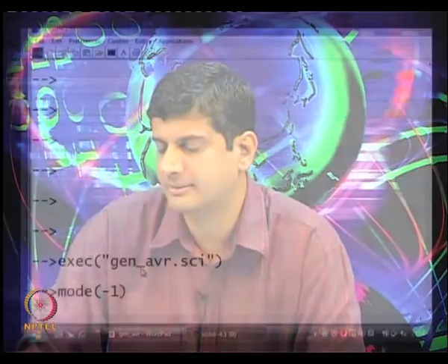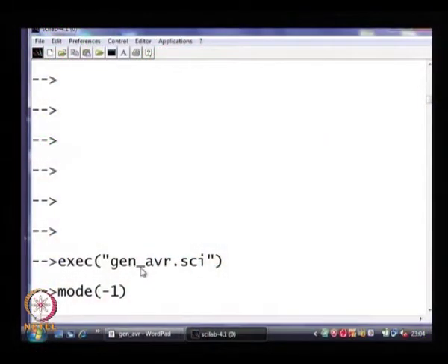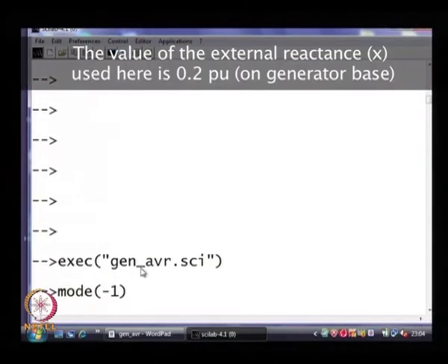Okay. And after 15 seconds, of course, the step in real power will be given at 5 seconds. After 15 seconds, we will give a step change in the reference value of the AVR. Okay. So, that is what we will simulate and close this lecture thereafter. Okay. So, if I simulate this, I am simulating for 25 seconds with Euler method with a time step of 5 milliseconds.